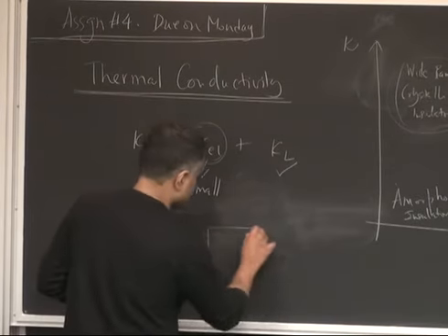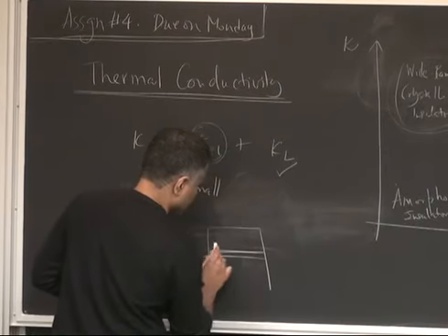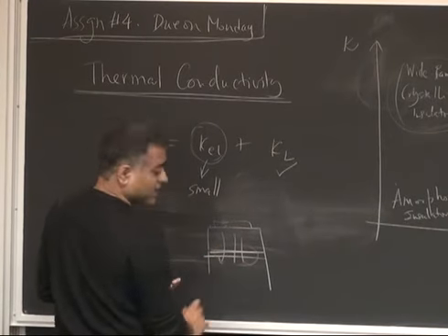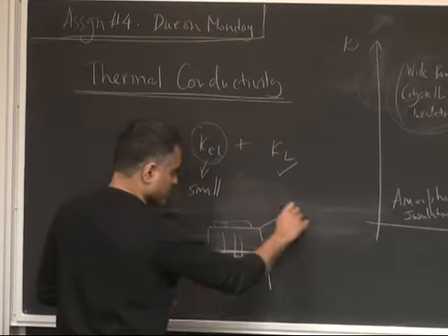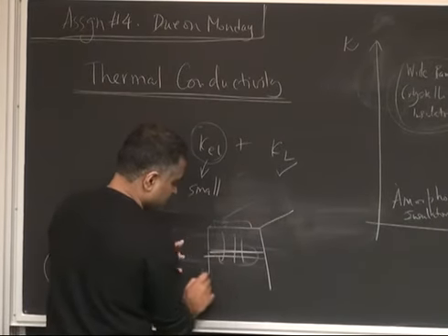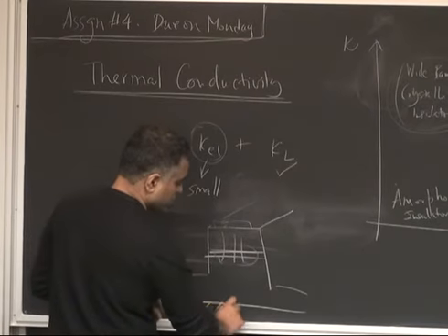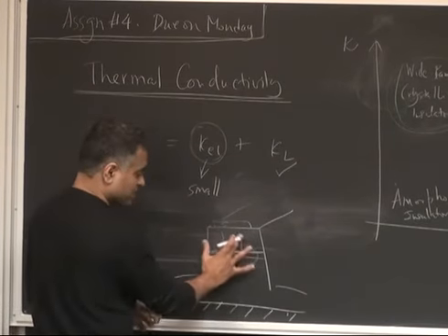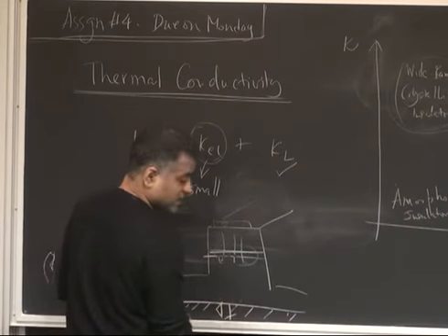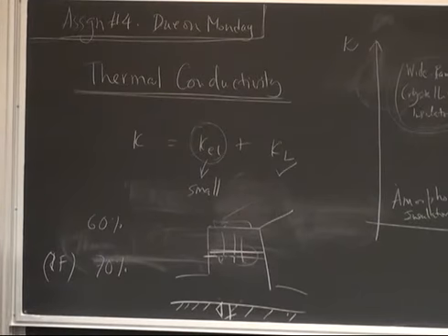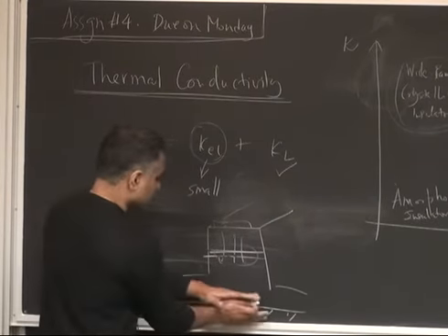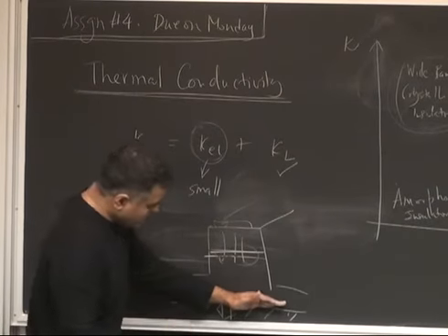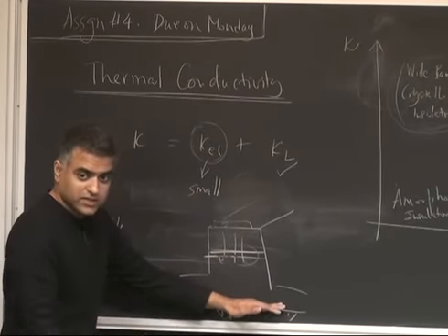And typically, for example, if you have a laser, we saw the laser structure, you have these quantum wells, and then you have cladding regions and all that, you have injection regions, right? So most of the heat is really being generated in the active region, where you get your spontaneous emission and stimulated emission. But the heat needs to be dissipated, so many times you will have to load it onto some material that's reasonably close to this, but not too close, so that you don't start messing up the device operation, and that is there to sink the heat. So there'll be a lot of active cooling, passive cooling and such. For those, you want this structure to be completely electrically insulated from the cooler that's going to drive the heat out, but you want it to be thermally shorted to it. So that's where you go then, right?